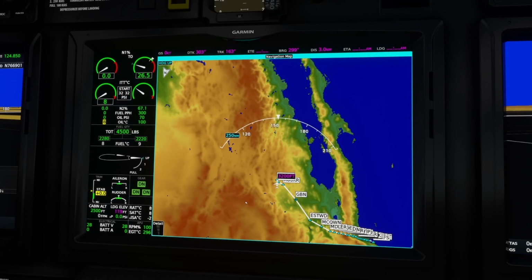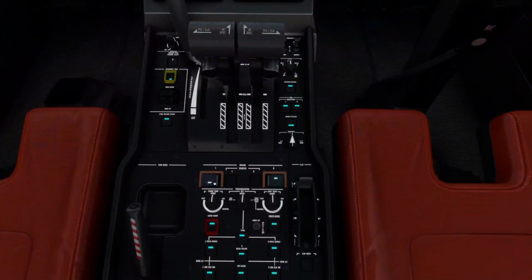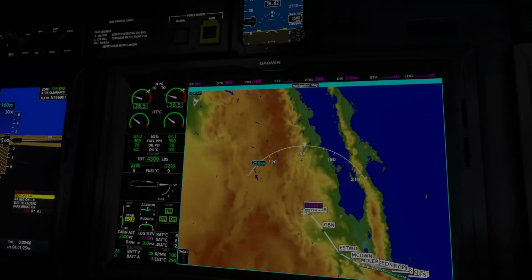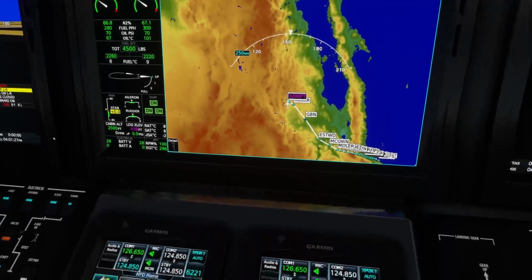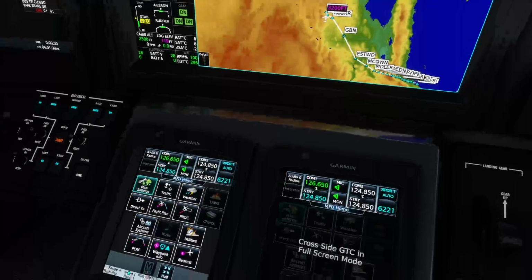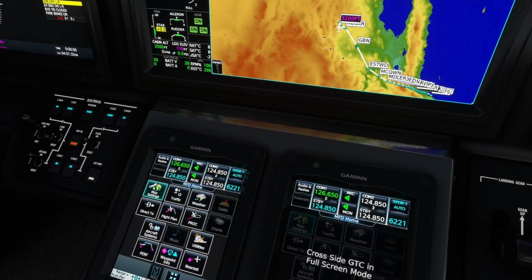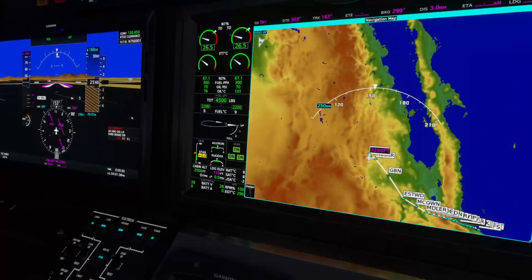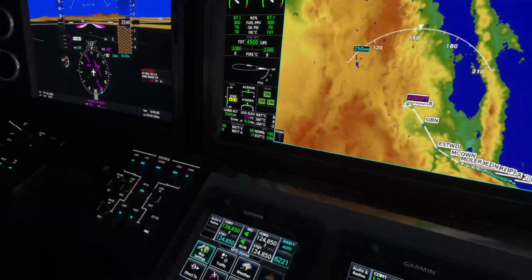All right, let's hit rinse and repeat for number 2. Actually, I guess technically that was number 2, so let's start number 1. So there's the run switch, there's the start switch, back up front, monitoring the engine performance. All right, beautiful. Two good starts. So now we're just going to step right on down here, do a reset on the left gen, flip it up, do a reset on the right gen, flip it up. That should solve the gen lights, as you guys can see there.